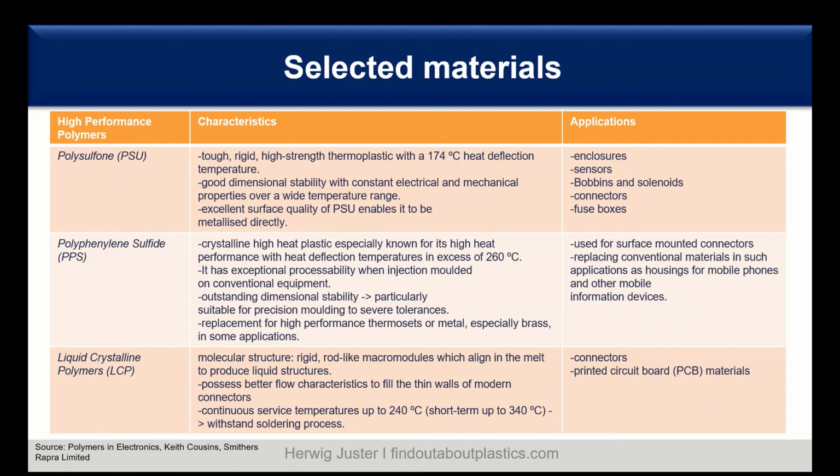It has extremely good flow properties, and this allows you to mold really thin walls of modern connectors. We have also continuous service temperatures up to 240 degrees, short term even 340 degrees C, and there is no problem to use it in the soldering process. And this you can see also in the application, so it's used for connectors, thin wall connectors, printed circuit boards, everywhere where you have the reflow soldering process.